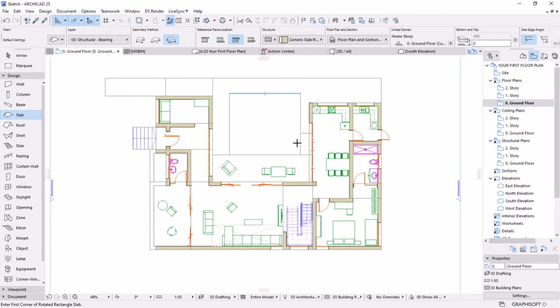So for this area, this will be a slab. I'll activate the magic wand tool because I have this, or I can just use the geometry method of placing a rectangle and then draw a rectangle where I specify the first point and diagonally moving to specify the second point, like that.